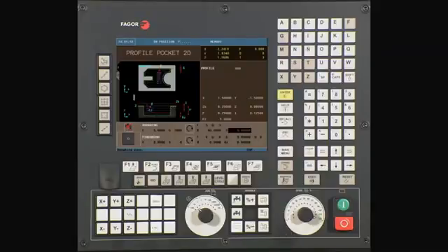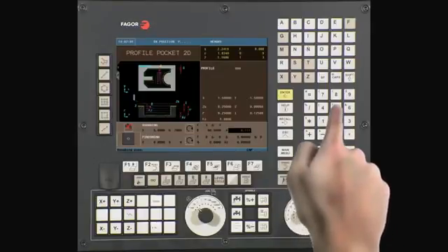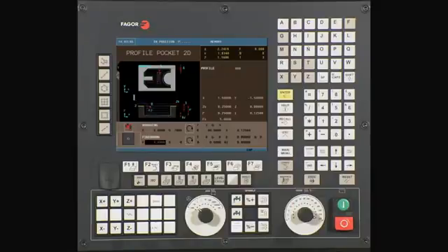Press Enter to continue. Note, when using a non-center cutting end mill, you will want to select a suitable ramp angle. Example, 5 degrees. This is your step over field. In this example, we'll be using a value of 0.125. Press Enter to continue. We will not be doing a finish pass, so please confirm that our finish tool is set to 0 under the finish section.